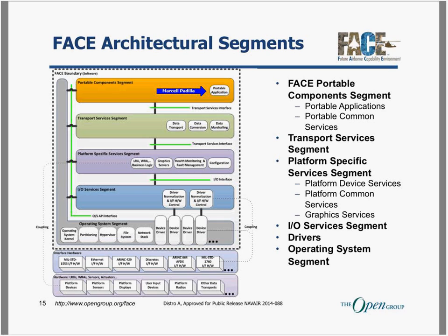Once the data come through any of the components here that needs to be consumed by my business logic, it will go through the transport services interface. Transport services interface is, again, another normalized interface, very simple: open, close, read, write, send, receive, and callback.